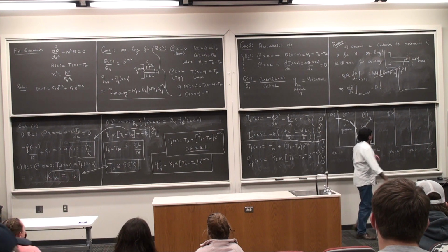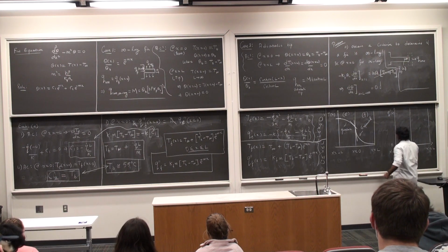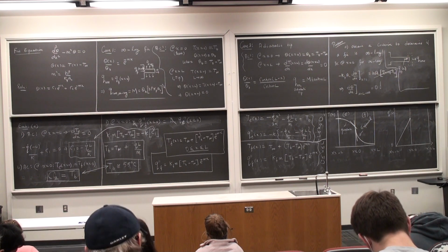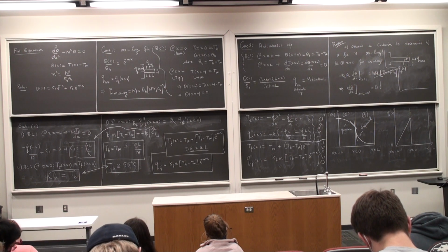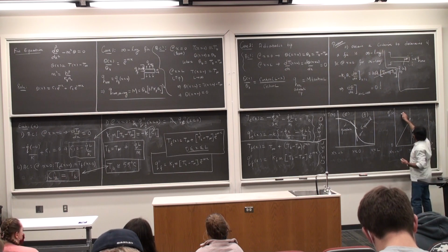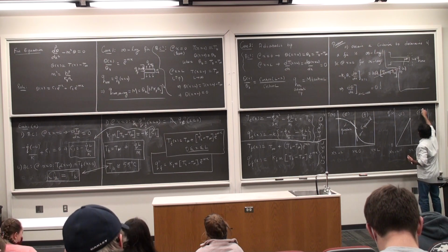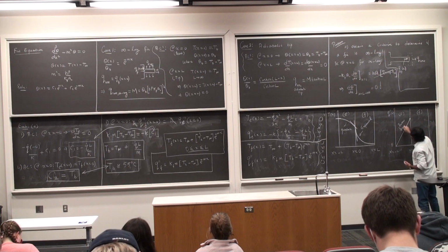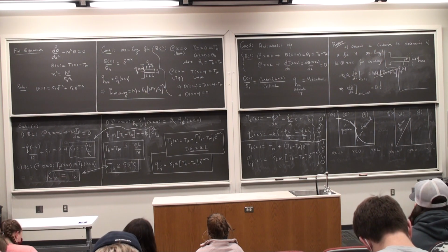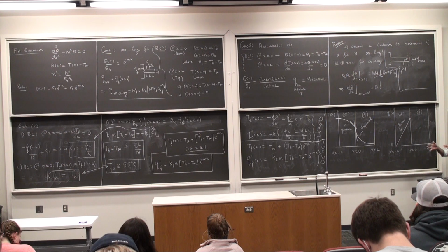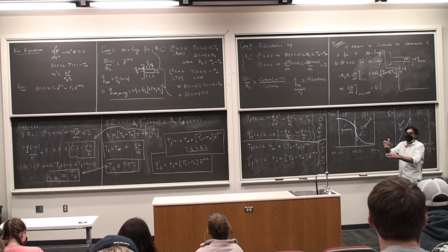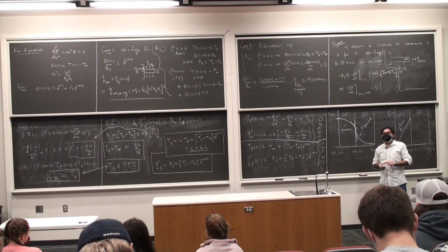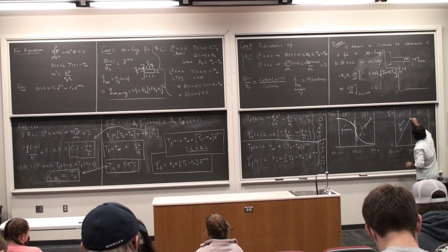So my heat flux starts from 0, goes all the way up, reaches a point where there is continuity between the embedded and the fin portion. This is linear. And obviously I know that this is an infinitely long fin, the tip being adiabatic, so I'm going to have an exponential decay where the heat transfer rate eventually falls down to zero. So this is going to be an exponential.